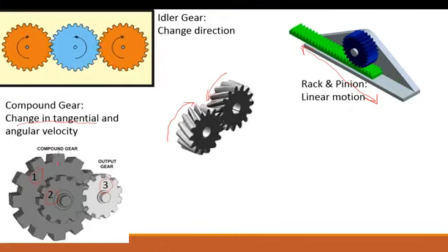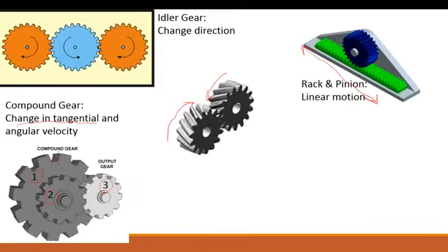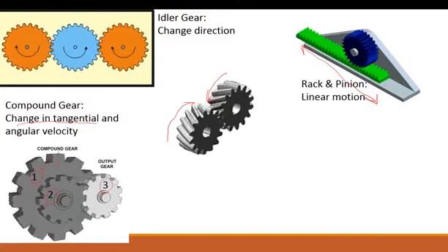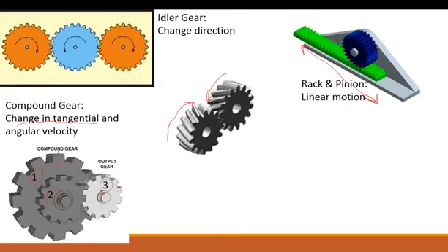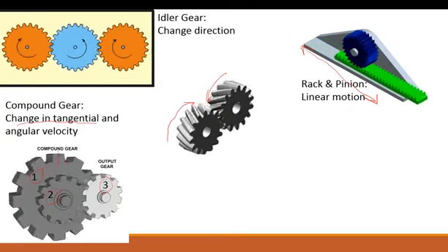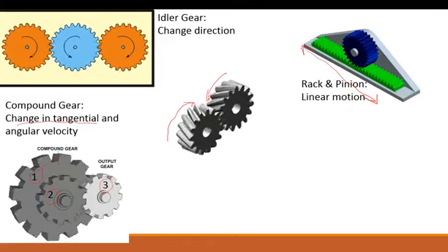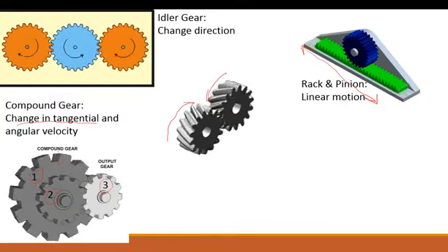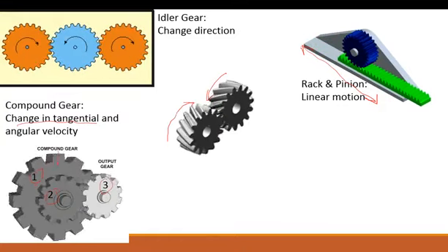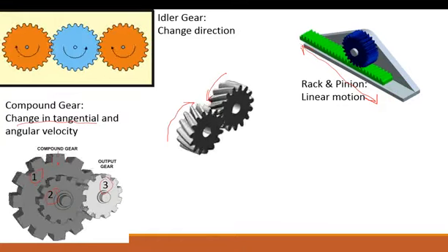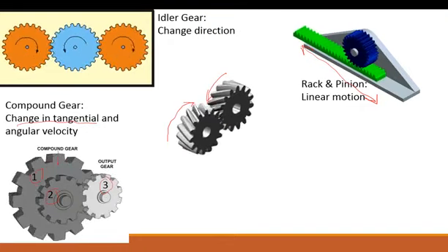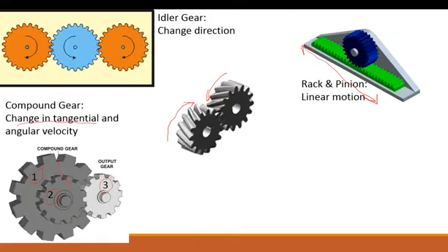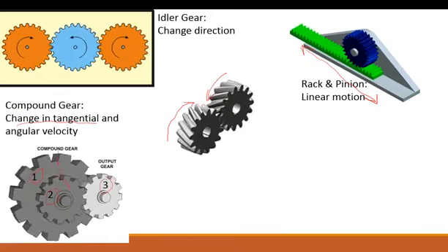This is oftentimes when you have step down gears or step up gears, multipliers, sometimes they're called reduction gears. You're using compound gears. And because of this difference in the two diameters, you can actually step the tangential velocities up or down accordingly, because the ratio stays constant. So what you have here is two gears on this compound gear that have a common angular velocity, but proportionally different tangential velocities based on their radii or diameters.